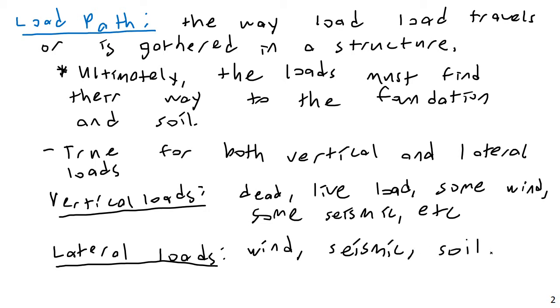If you have, say, a retaining wall. Let's say you have a hillside and you want to build a lot on it. One thing you can do is carve out a portion of that hillside and build a structure there. But to keep the slope from reestablishing itself, you build a retaining wall, and then you fill this in with something. Your retaining wall would have its own self-weight, but also the lateral pressure load and overturning moment from the soil. So pressures can be a lateral load.